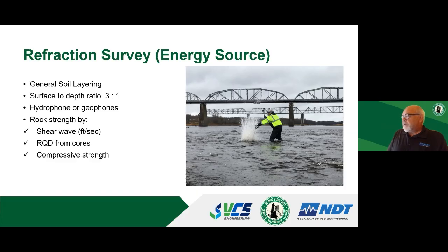So this is an example of some knee-high water where a barge or a track-mounted drill rig would have been really challenging to get in there. And we were able to use our hydrophones and come up with a complete rock profile, which was the objective as they were sizing the span lengths for a new bridge across a river. And we got about 1,400 feet in 2 days. I've got a case study that will expand upon this.